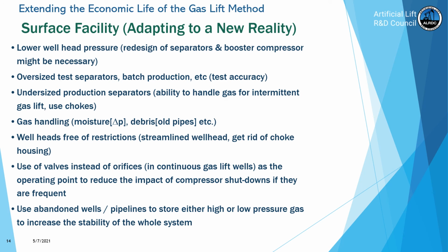Yes, you're going to create a temporary increase of the back pressure of that particular well, but you're going to eliminate the problem at the separator, which might be a problem that will not allow you to produce the well at all.